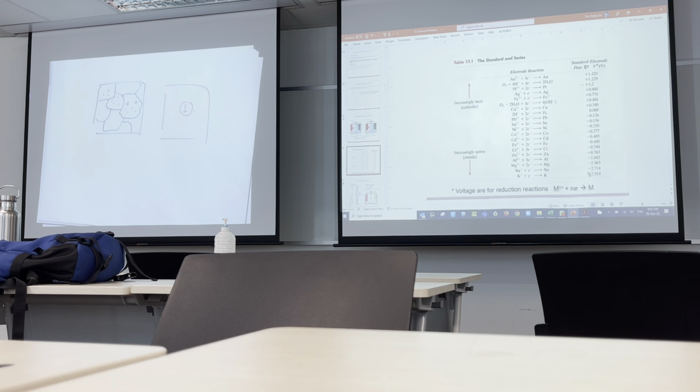Why do you need to polish? Because we polish, we actually have a flat surface, so it is easier to see them, a mirror finish. Remove all the scratches so that when you look, it's really just the grain. If it's not shiny and you have a lot of lines, you don't even know whether it's the grain or whatever. So we always polish to mirror.